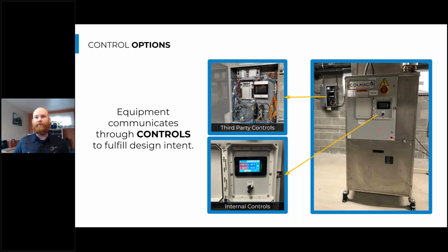Pretty simple, but essentially we're going to set that system up to target a delivery water temperature, and then have a thermal on and off temperature, or thermal on and off engagement based on the temperature sensor in the tank. This is a third-party controller that we have at Jackson Apartments, and we are logging or measuring the system performance here, looking at how efficient the system is as a whole.